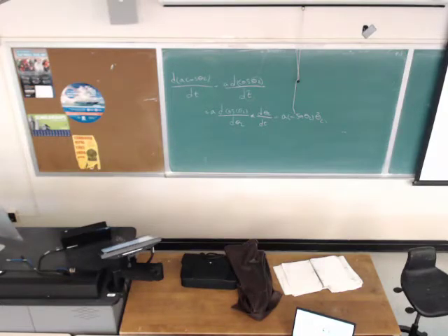In MATLAB, you enter matrix A as 1, negative b sine of theta 3, semicolon, so 0, b cosine of theta 3. B and theta 3 are now coming from displacement analysis.